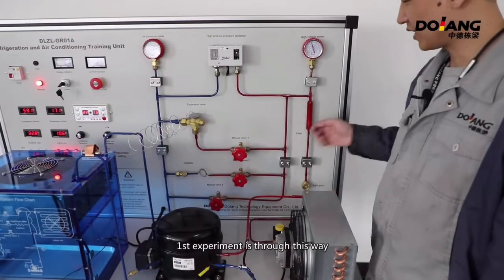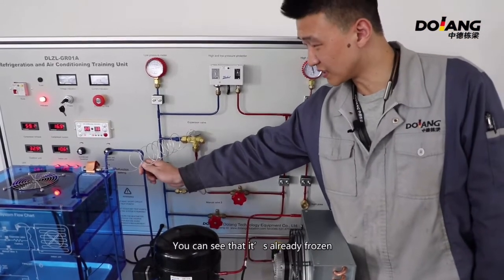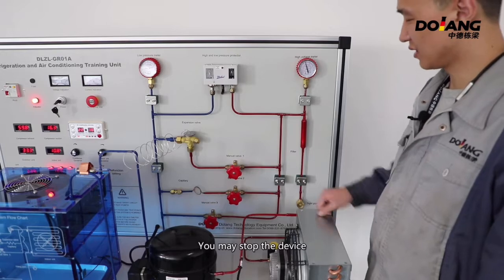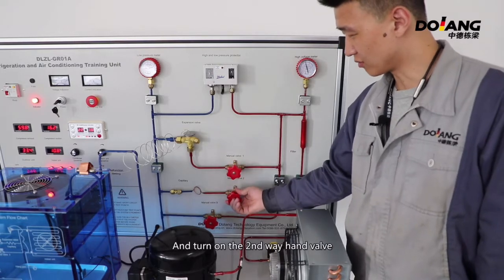The first experiment is through this way. You can see that it's already frozen. Go to the second refrigeration line. You may stop the device, turn off the first way hand valve, and turn on the second way hand valve. Make sure the other 2 ways are closed.